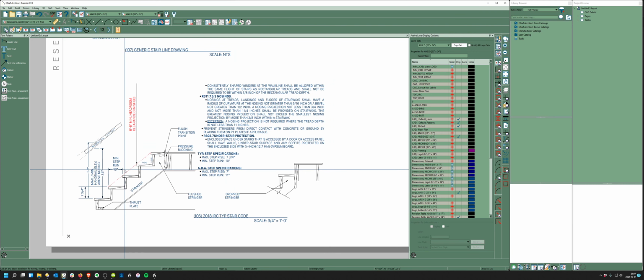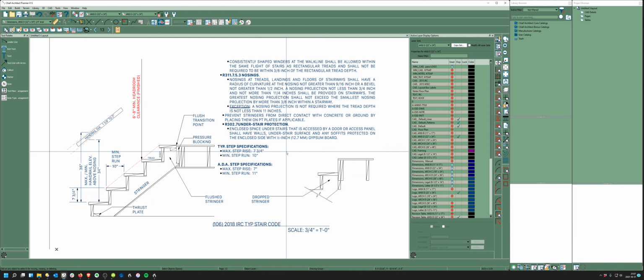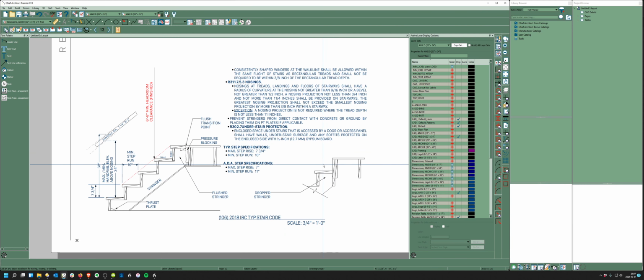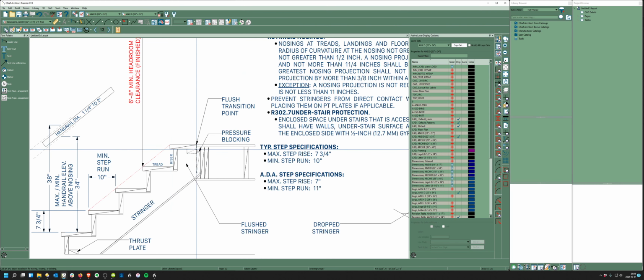So this is cool as a framer. I always like to build my stair stringers like this because I feel that's stronger, but some people like to do a drop stringer. The only advantage is that you can use shorter lumber by one notch cut. I like these because you can plane everything to where you actually use a partial tread at the top.